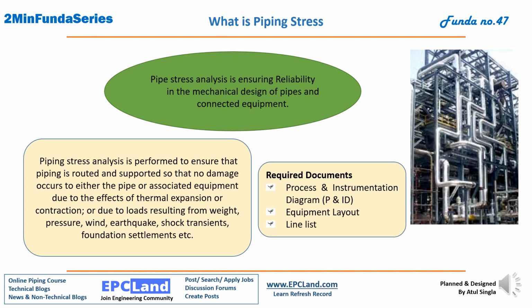So at different times there will be expansion or contraction, thermal expansion or contraction. So everything we need to take care of. To take care of all these things, we perform stress analysis. In stress analysis we ensure that piping is routed and supported so that no damage occurs to either the pipe or the associated equipment. To perform the stress analysis, the stress team requires process and instrument diagram, equipment layout, and line list.